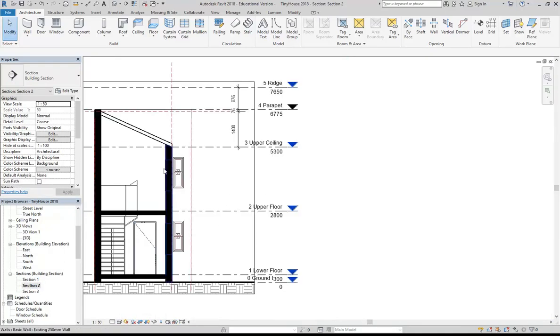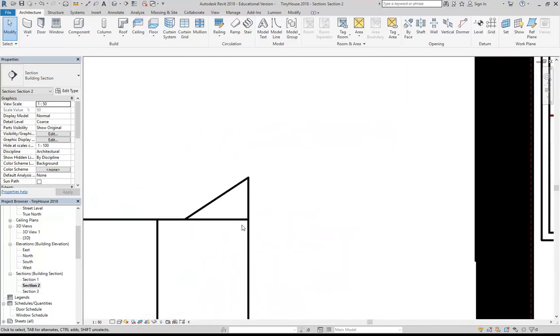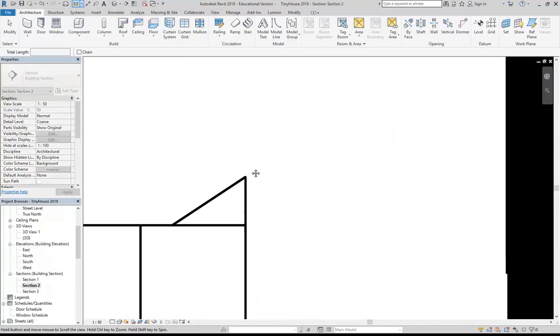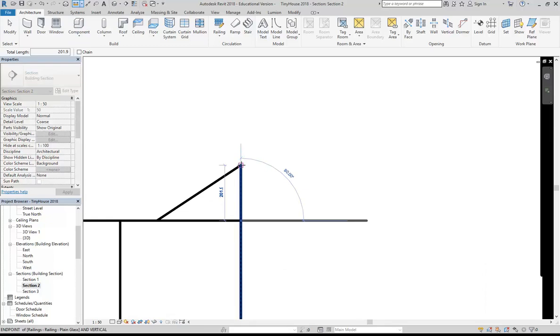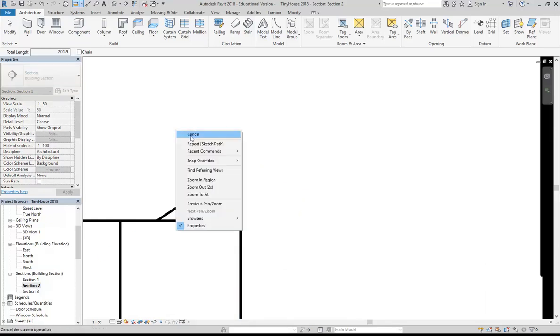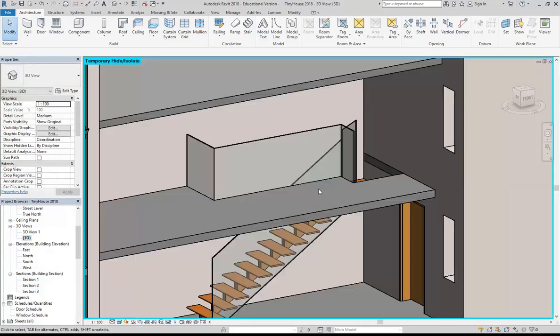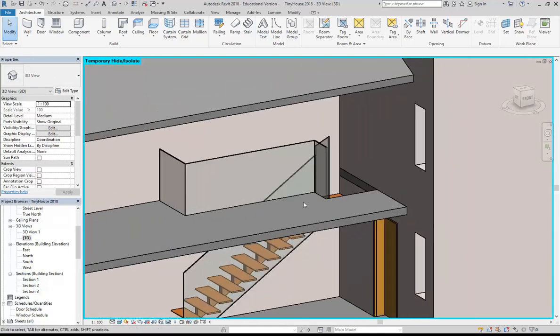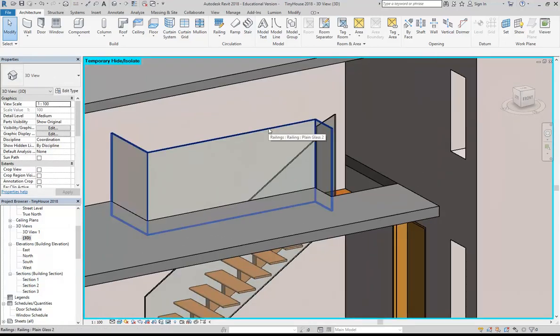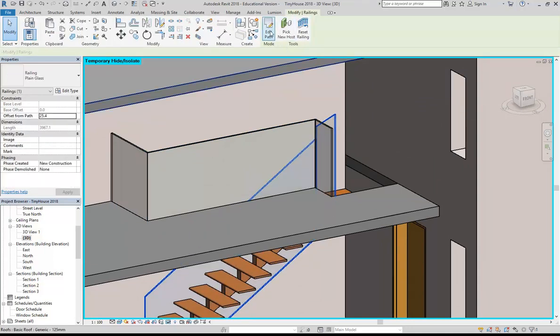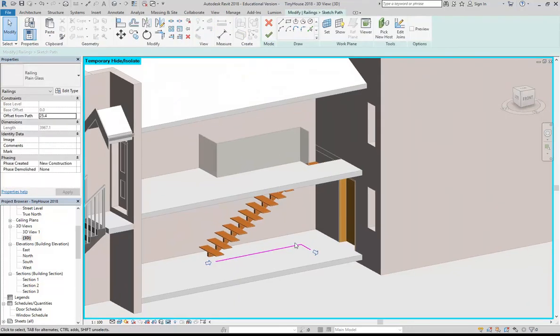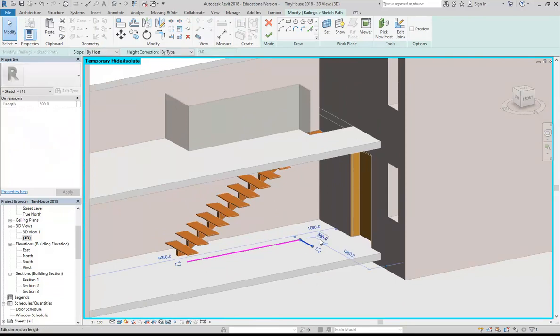There we are, so I can see it there. So I can then measure what my height correction has to be. So I'll just measure that distance there. What is it? 200, that's quite a bit. Okay, so I've got to go back to the 3D view. Okay, so to finish this off, I'll have to start maybe with that one. Edit path, and then I can select this line here.